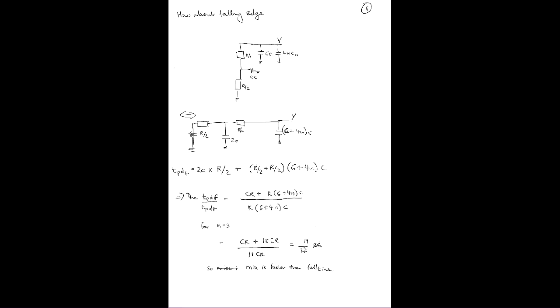Okay, so that just gave you some of the machinery and some of the insights to start understanding how, if you had a couple of gates and you put them down, you can work out some of the capacitances and resistances in order to work out the equivalent models, the equivalent Elmore delay model, in order to be able to estimate the propagation delay.